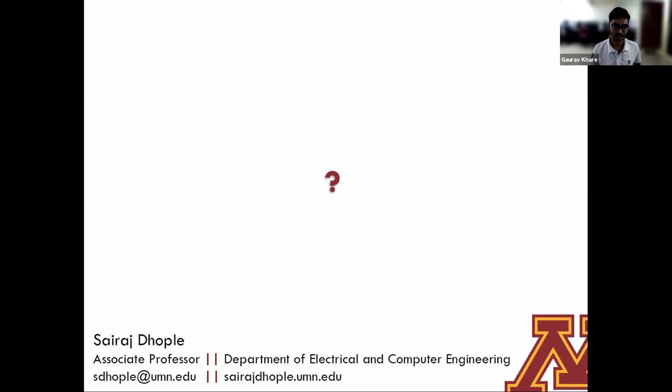So the second last question is, what about the THD levels? With the nonlinear oscillator, does it lead to bifurcation if not properly designed? Okay, so now there are many different types of nonlinear circuits, and they all have very complex dynamics. The ones that I showed you that we are using belong to a class of systems called Liénard systems, and they have very well-defined oscillatory behavior. In fact, there are lots of analytical guarantees on its performance. So you do get much more guarantee that you will always get to sinusoidal steady state operation. But yes, this is something you have to be aware of in nonlinear systems.